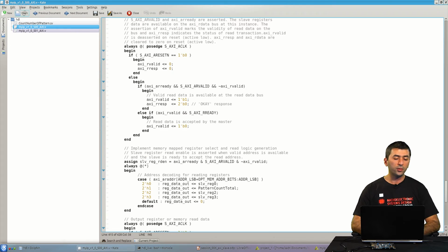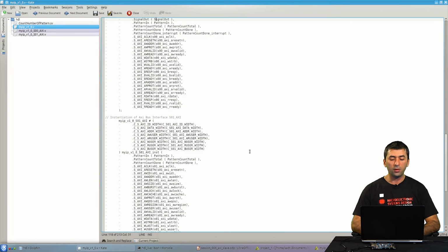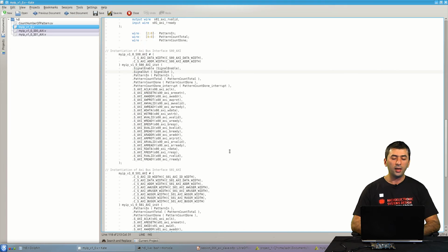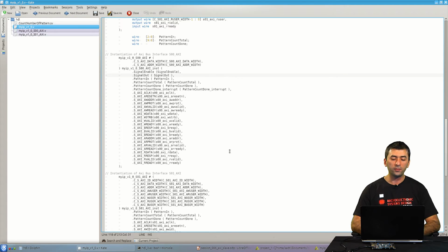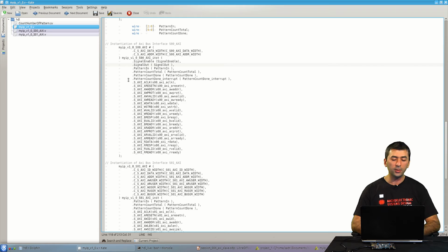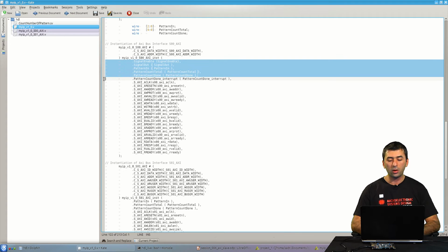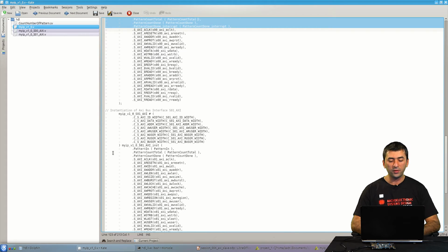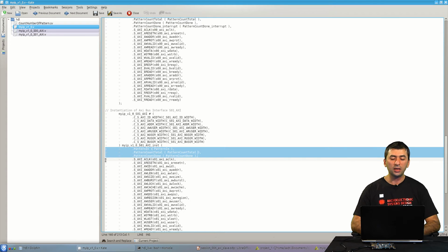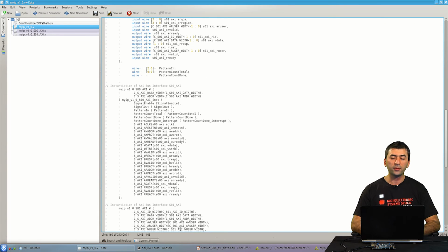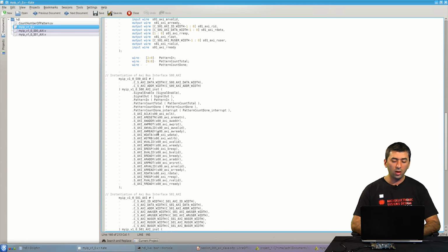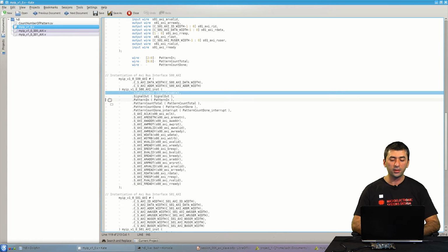Now I go back to the top level. The top level of the module is actually the same two AXI plugs that I showed you in the beginning, but the ports are updated. So we have a set of ports which are connecting these two AXI plugs together, and I have these ports which are practically going to the outside world.